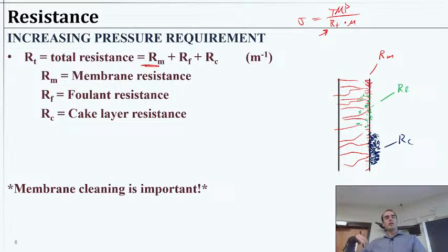And then perhaps, in that particular scenario, they would chemically clean them every 5 to 6 months. So they'd give it a chemical cleaning to get all this stuff away, but they would be shaking it and doing these other things to try to really keep any cake layer from forming and clogging things up. All of that will depend a bit on how exactly the membrane is designed and how it's operating, but typically the backwashing happens with a lot more frequency than for the granular media filters that you have to drain and backwash, like we saw.